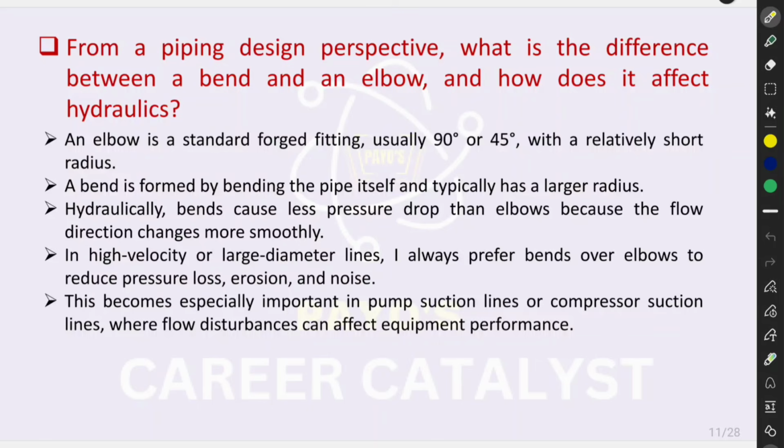Hydraulically, bends cause less pressure drop than elbows because the flow direction changes more smoothly. In high velocity or large diameter lines, I always prefer bends over elbows to reduce pressure loss, erosion, and noise. This becomes especially important in pump suction lines or compressor suction lines where flow disturbances can affect equipment performance.